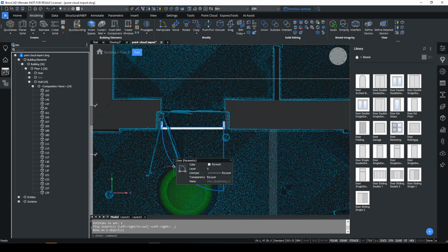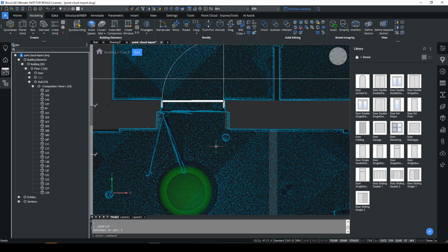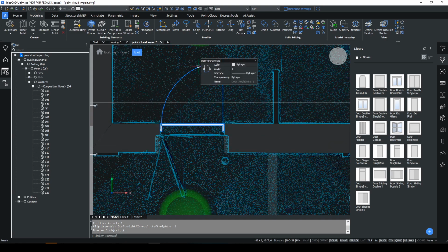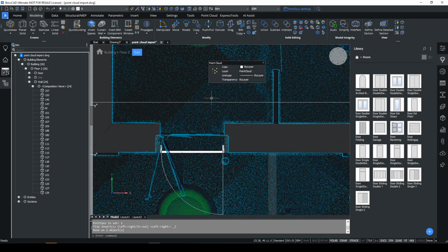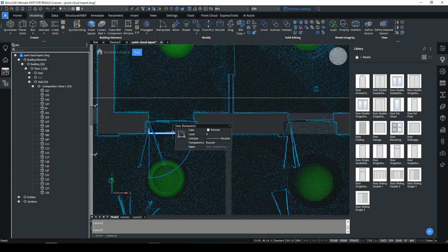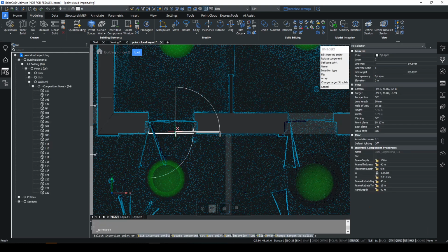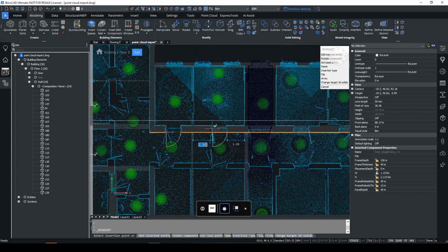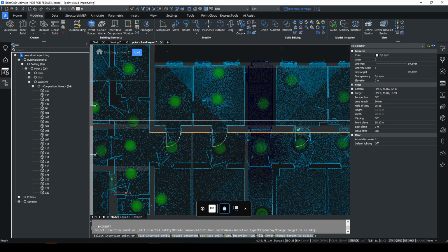So depending on what exactly you need to get done. And all you would do in this case is, if it's a situation where there's multiple versions of the exact same door in the building, you will get one done correctly, hover over that, and use the BIM insert command to effectively copy that, and then just move around and place that in all the relevant locations around that building.